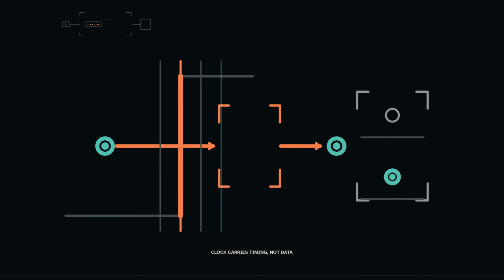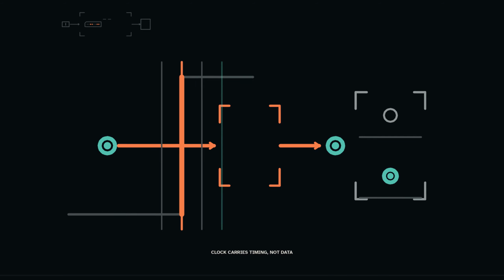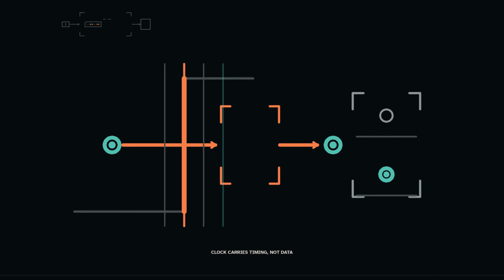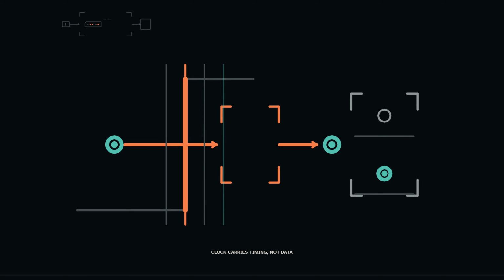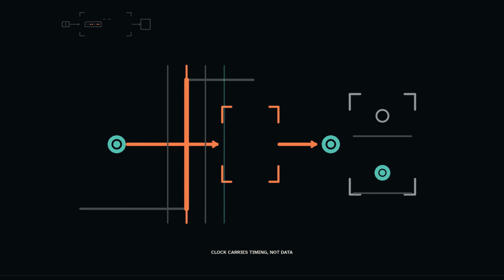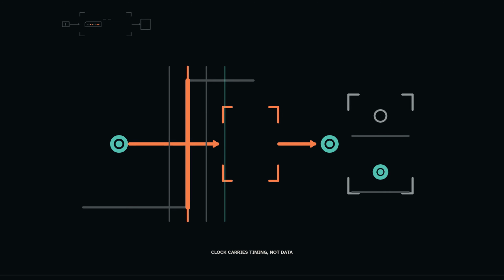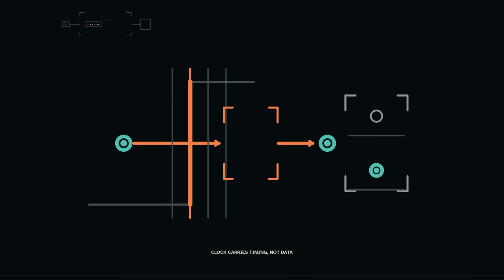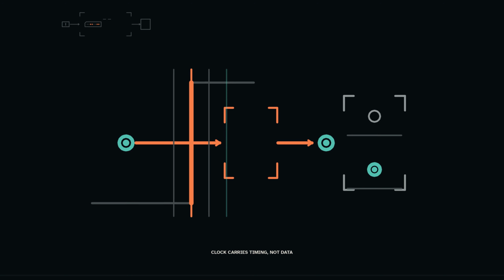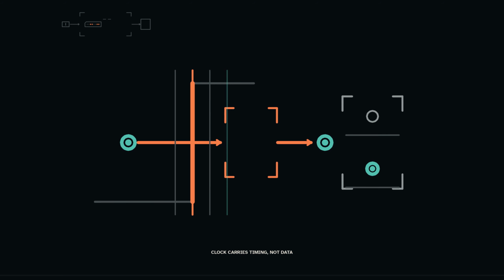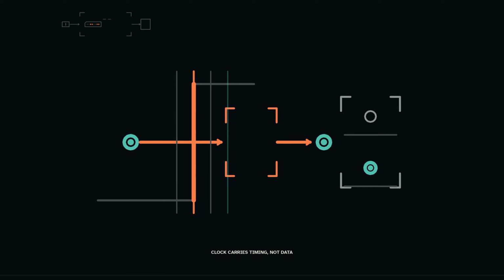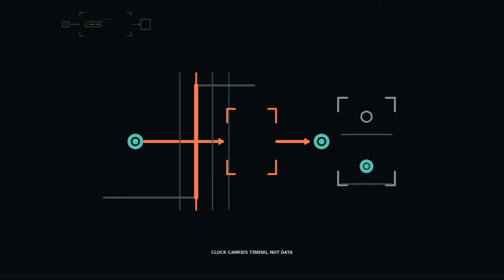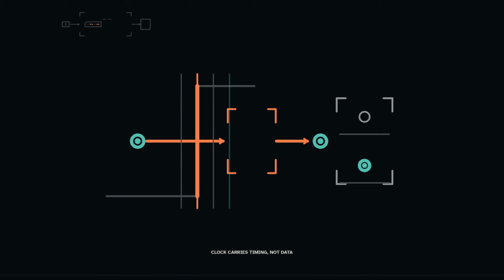A clock is not universal time for the entire world. It is a physical signal distributed to a chosen timing domain, with finite rise time, delay, and differences in arrival called skew. Designers choose a period long enough for required paths to settle and timing constraints to be met. Some systems use different clocks or asynchronous methods. Our teaching machine uses one declared synchronous model because it makes each committed state change inspectable, not because every computer component in existence changes on one perfect tick.